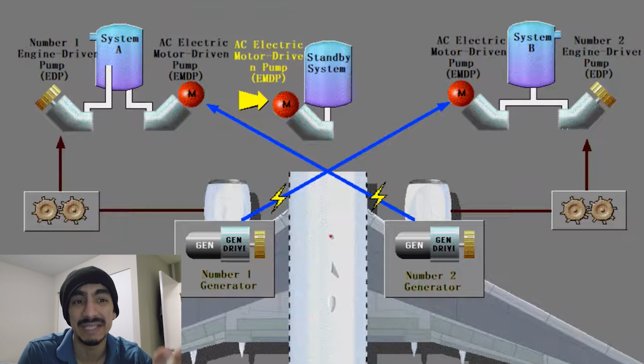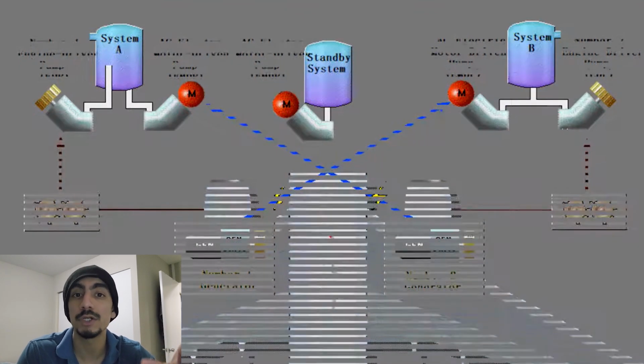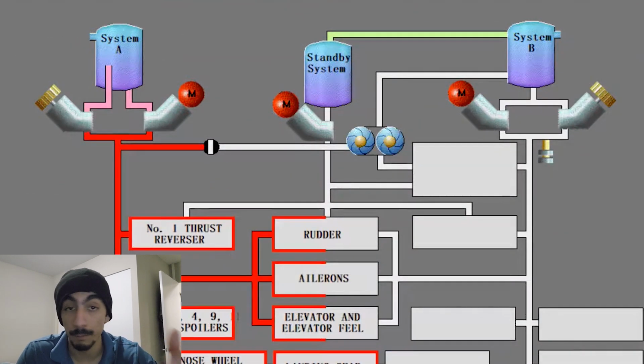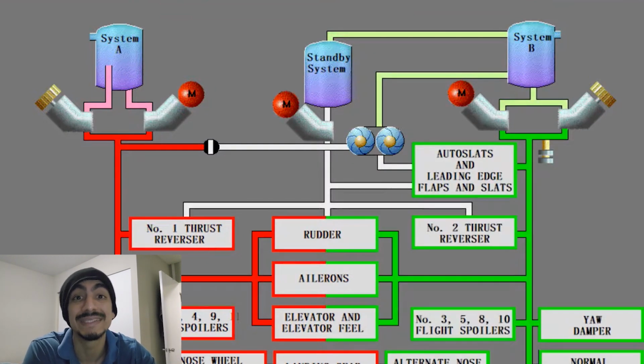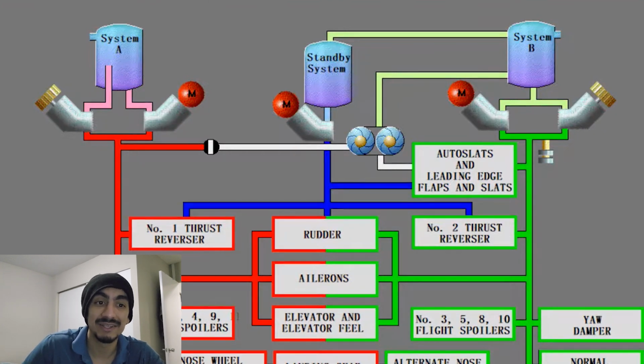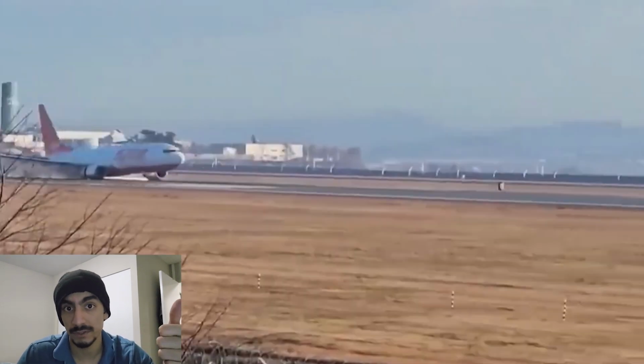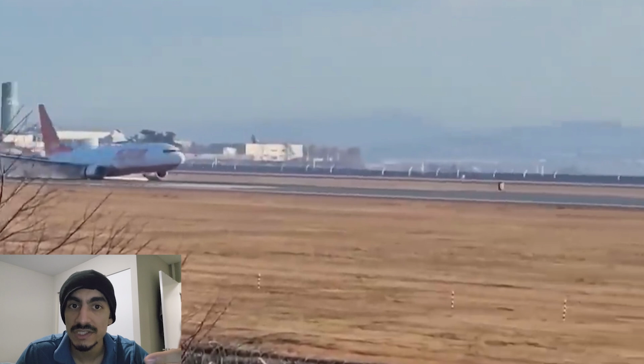And what's key here is that the 737-800 and most modern jets have 2 or 3 independent hydraulic circuits. So if something punctures one line, like debris or a bird strike or metal fragments from a damaged engine, there's still another circuit pressurized and ready to handle the same tasks. You never want single points of failure to take away your ability to steer or lower the gear. So the first layer of redundancy is a second engine being available. The second layer of redundancy is that there are multiple hydraulic lines. The third one is electrical power, okay?